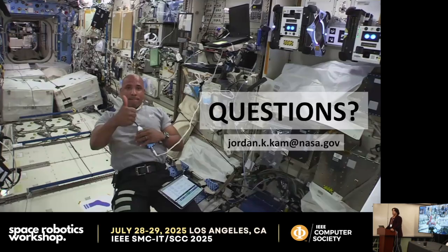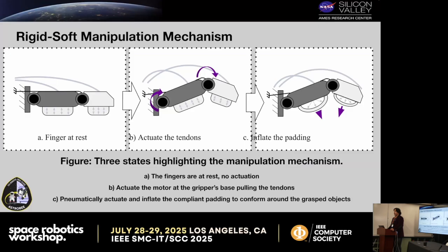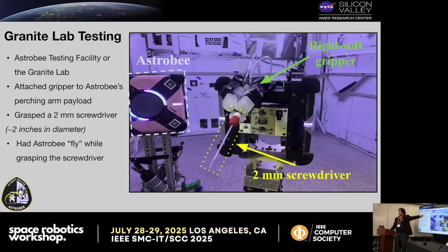Yeah, it's silicone 0030, it's an elastomer. When you actuate the soft part of it, you say it's pneumatically controlled. Do you have force control on that, or is it just on and off? We don't have any force control on it. We have it connected to the pumping lines that you can see, and to a syringe, which is very common for demonstrations in soft robotics. So technically you could probably have some control, but for this we did not have any actual pneumatic control.